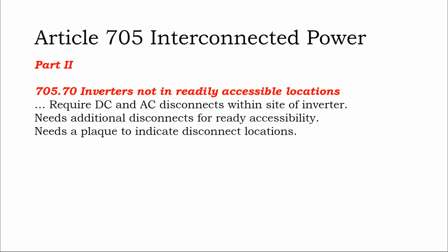And if these locations are not both adjacent to the solar array, then you need to have disconnects in both locations.